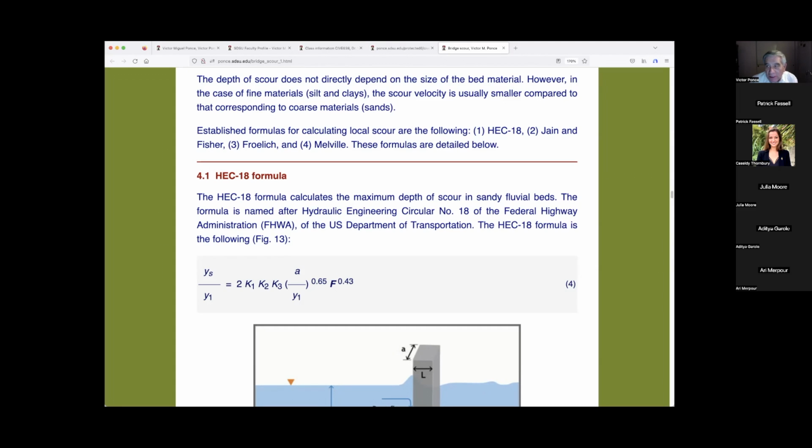And by the time it gets there, you're going upstream, getting to be a little gravelly bottom. So that's not very common. Most rivers are in that range, 0.001, plus minus a reasonable range for the slope. And therefore, that is the location where you're going to find sand in the bed, different types of sand.